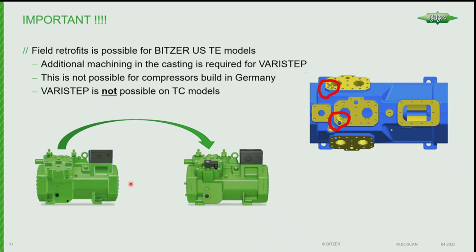So as long as you get oil back to the compressor with mechanical unloading, you won't have that issue necessarily. But if you have a large rack and it's a really cold winter and you're down to one compressor and you're going to load it, you're still going to run into that same issue. You're not going to have enough mass flow through the system to get the oil back. So it doesn't really solve that problem, but it is an option to use in conjunction with VFDs or in place of